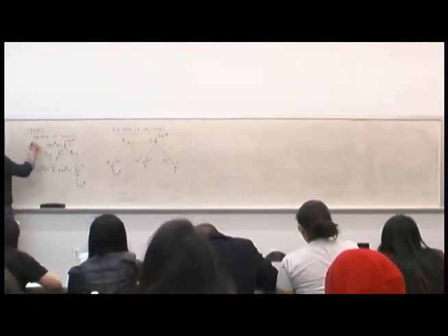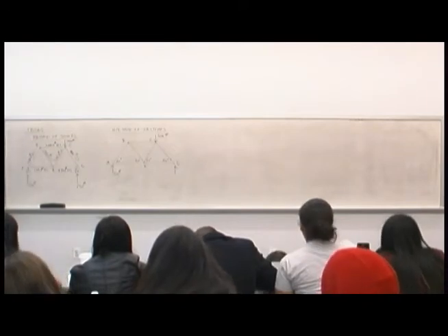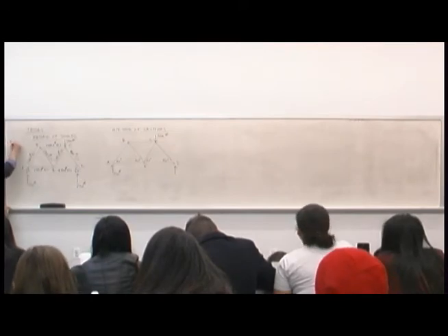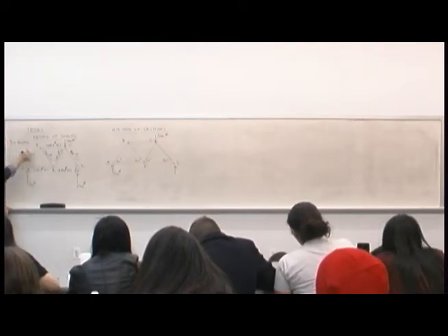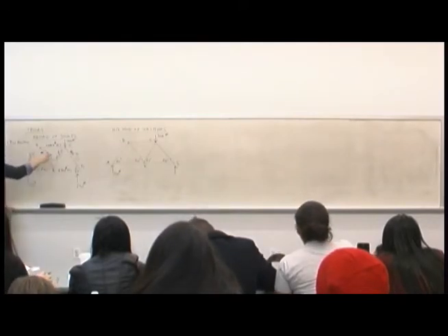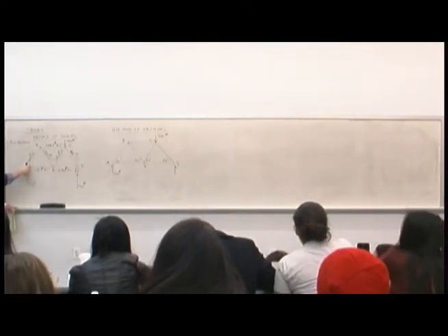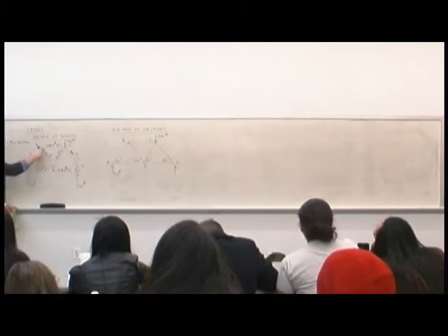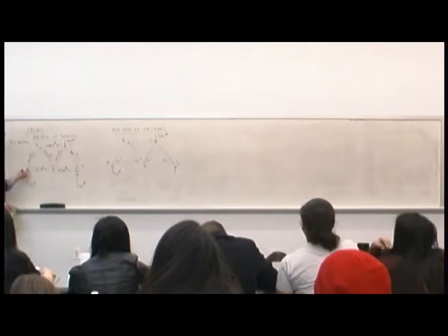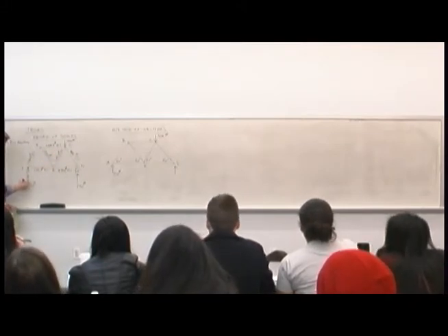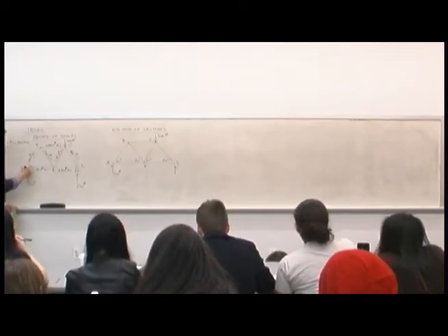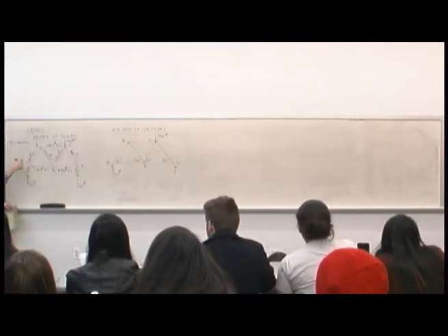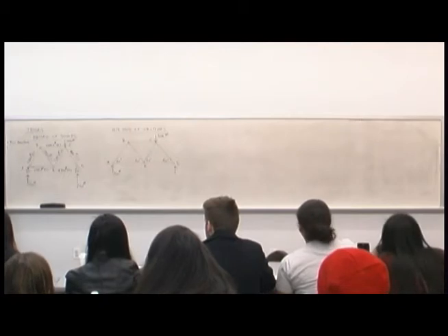So last week we did this truss analysis using method of joints, and what we did was we found the reactions, and then move from joint to joint to joint, balancing the joint in equilibrium, and then solving for the unknowns and getting the forces that we want at each location. So that requires you to think about the reaction, the members coming in to the node, whether it's in compression or tension, and balancing it like we've been doing in all the other equilibrium problems.